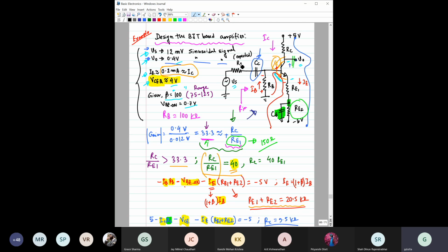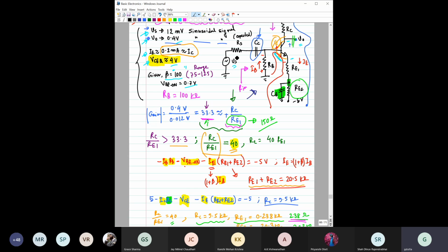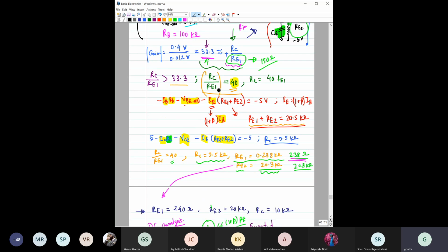But a couple of things, for example, what should be the value of this RS, I think we have not investigated. This RS value is actually the resistance offered by the source. Typically it is quite less compared to the other resistances that you are using in your circuit. It is not something you are including; rather, you are using some signal source, and the signal source will offer that RS. So if you know about the signal source, you should be able to find the resistance offered by that source.